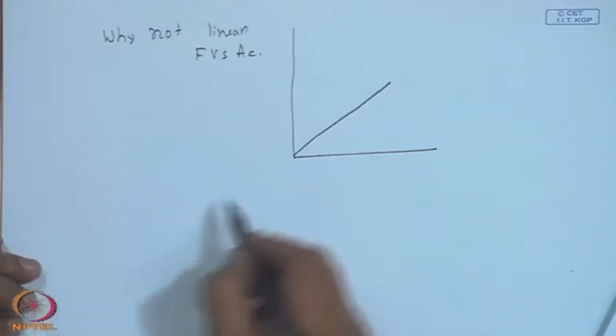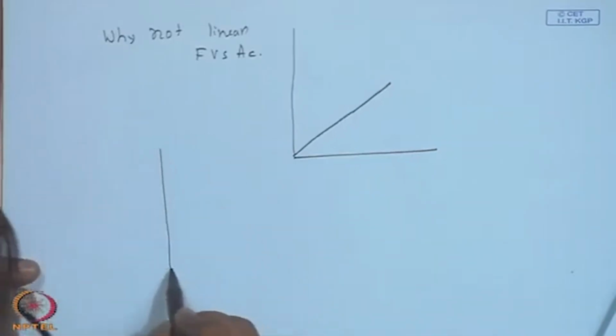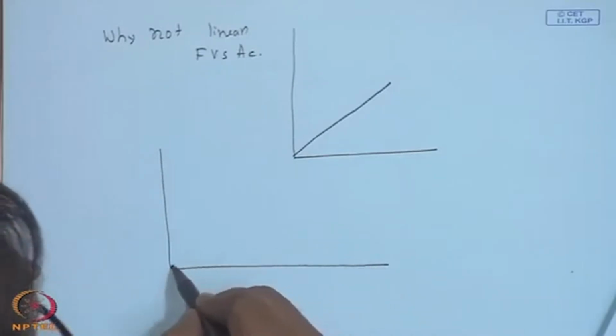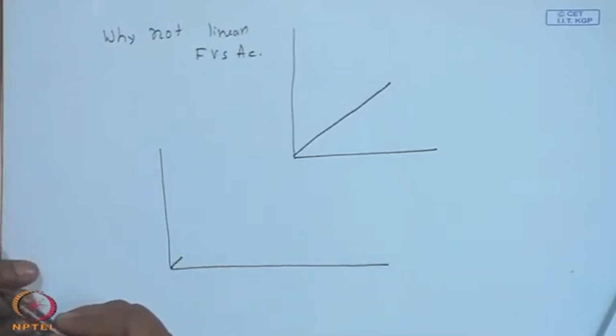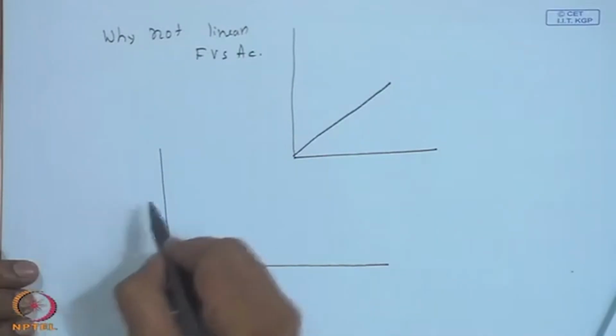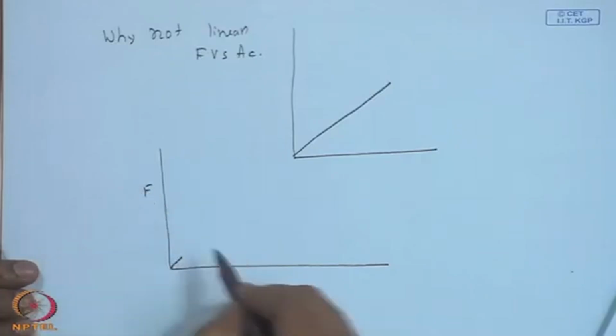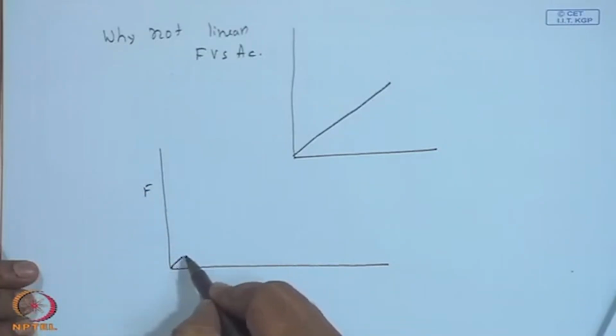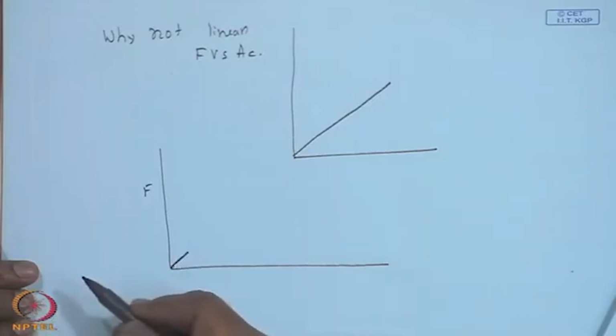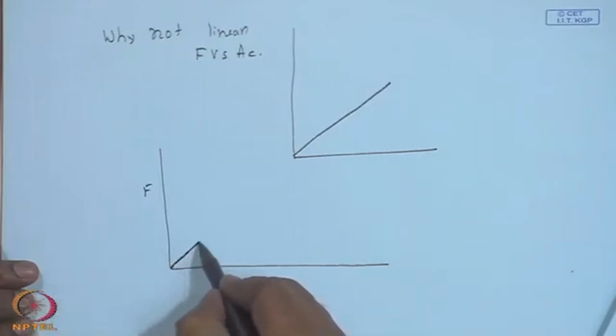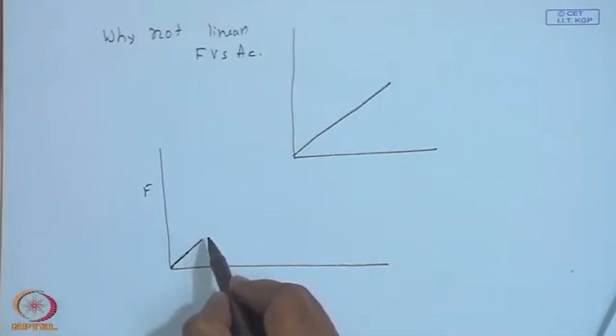So, at initial very small area, there is no question of energy being in excess of the load. As you double the area of the collector, it will double the utilization, consequently, it will initially be linear. Now, at a particular area, something like this, it starts meeting the load fully, let us say in the month of October.